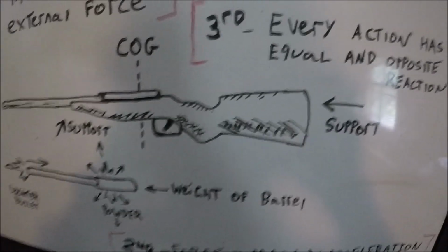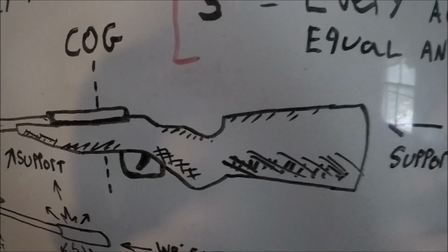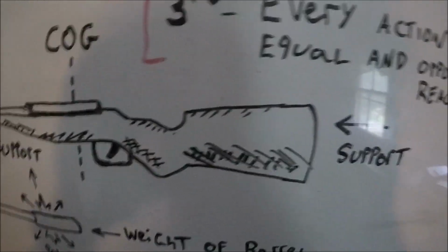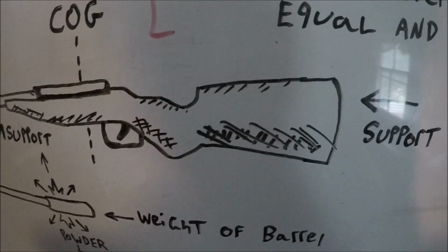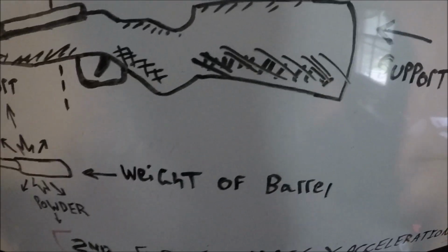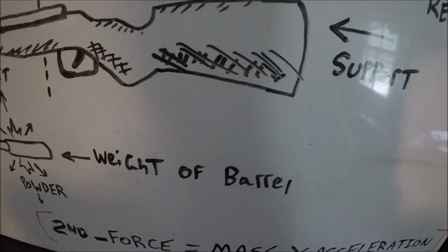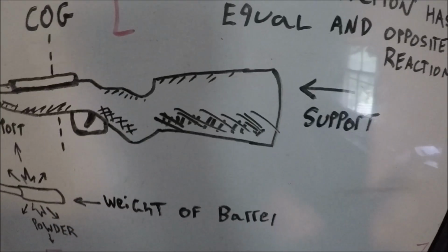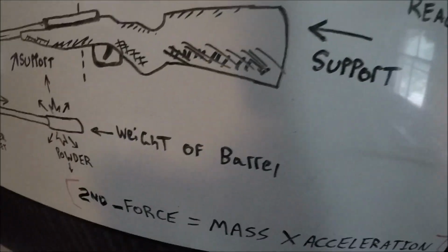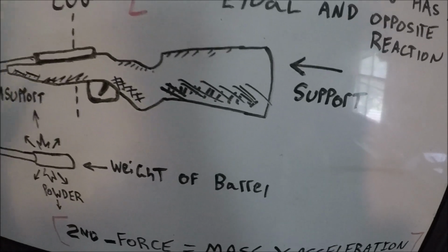So it's important to remember when you're looking at stock design, as the weapon system moves backwards, your body, if you're a right-handed fighter, the way it's shaped, the recoil force is going to want to come straight back, and that energy is going to follow the path of least resistance, right? And so it's going to move up and slightly to the right, hence muzzle rise and why barrels don't go down, and that force generally overcomes gravity.